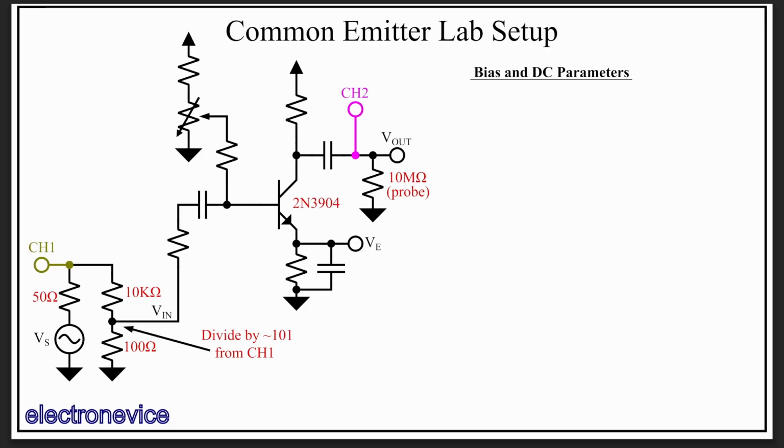Moving along, we have a series resistance from the divider to the rest of the circuit. This is the high input resistance we need to have in order to accentuate the Miller effect's negative impact on our circuit. The divider has a low resistance of slightly under 100 ohms, which is not conducive to showcasing the Miller effect. As a result, we need to add some additional resistance. We're going to set this to 1K, resulting in a total source resistance of around 1.1K.